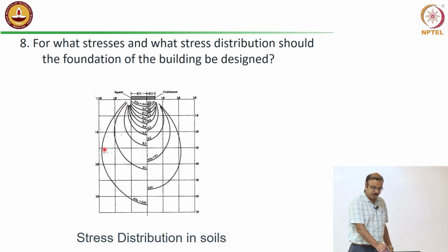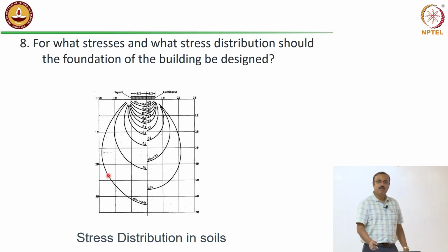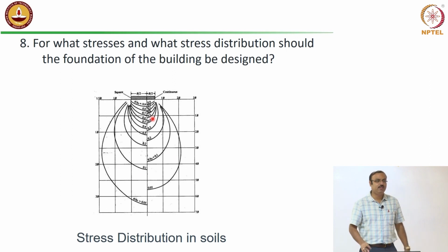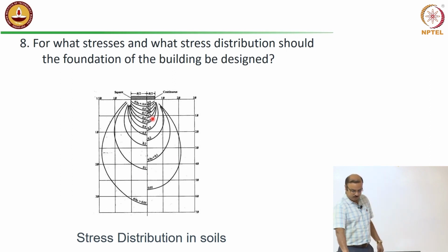It is a very important term, it is called the pressure bulb. So, the pressure bulb below the foundation is a zone where, due to the foundation load, the stress will be significant in nature. Whatever settlement occurs depends on the compressibility nature of the soil within this pressure bulb. So, the soil within this pressure bulb will compress, will get reduced in thickness.